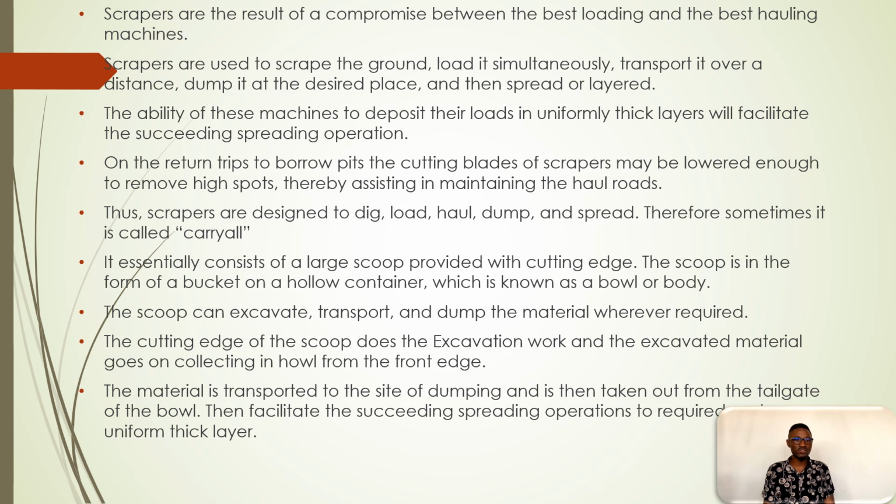On the return trips to borrow pits, cutting blades or scrapers may be lowered enough to remove high spots, thereby assisting in maintaining the haul roads. Thus, scrapers are designed to dig, load, haul, dump, and spread. Therefore, sometimes it's called a carry-all.